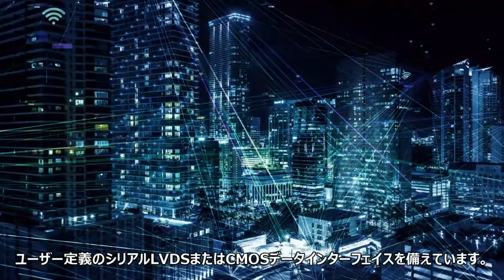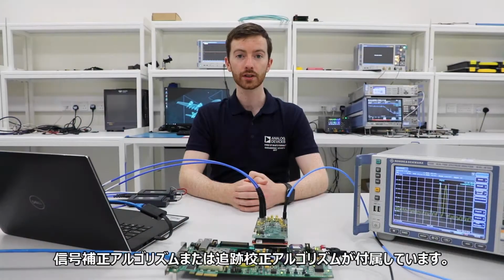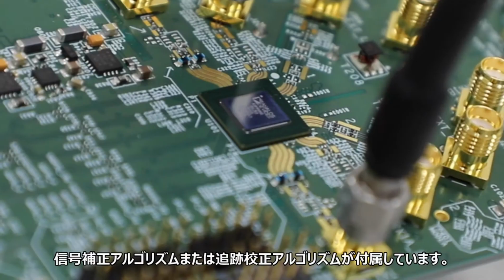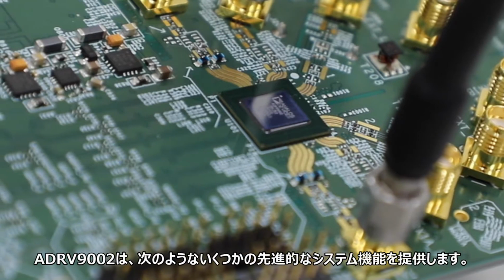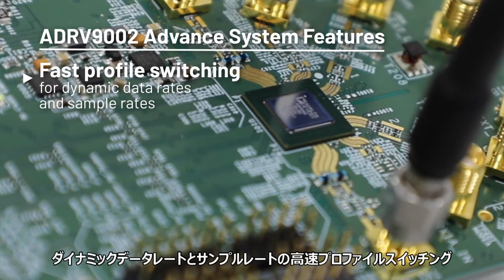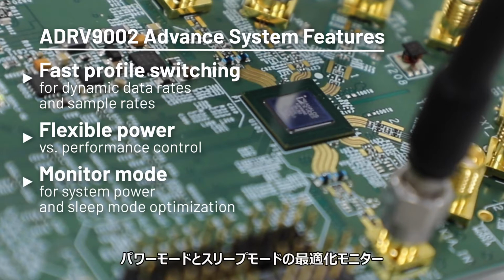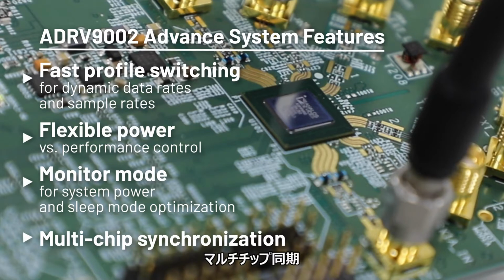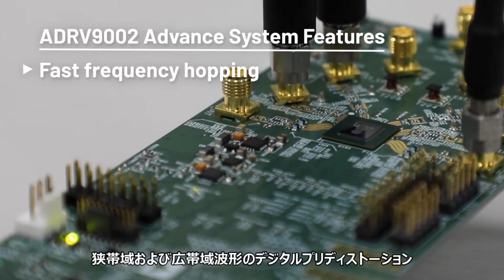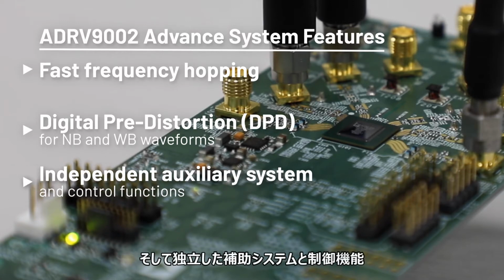It has a user-defined serial LVDS or CMOS data interface and comes with signal correction algorithms or tracking calibration algorithms. ADRV9002 offers a number of advanced system features, such as fast profile switching for dynamic data rates and sample rates, flexible power versus performance control within the analog and digital circuits, a monitor mode for power and sleep mode optimization, multi-chip synchronization, fast frequency hopping, digital pre-distortion for narrowband and wideband waveforms, and independent auxiliary and control functions.